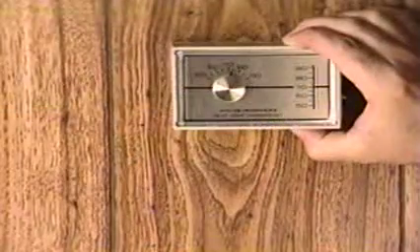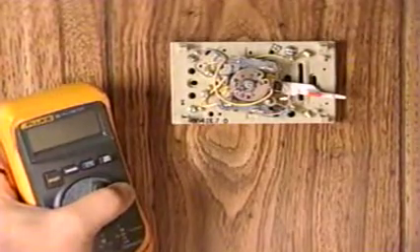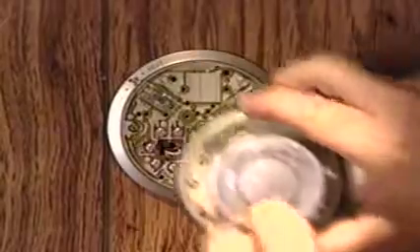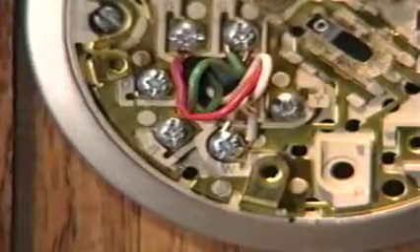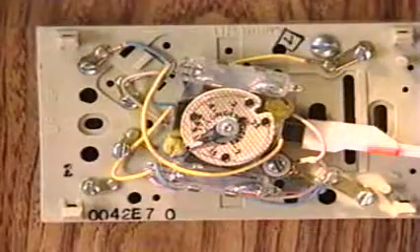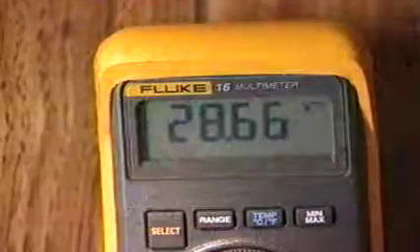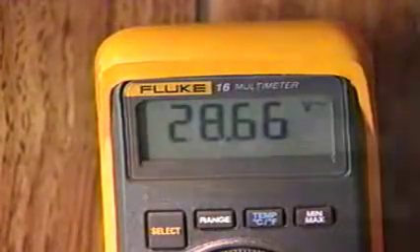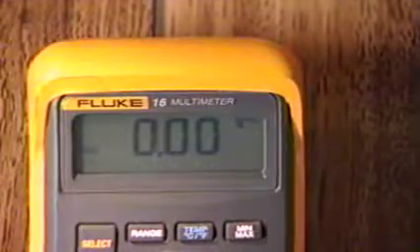A voltmeter is probably the most useful piece of test equipment when troubleshooting thermostats. Voltage readings are often taken at the sub-base, which is where the control connections are made for the thermostat. If the contacts on the thermostat are in the open position, there will be a voltage reading between the two terminals. If the contacts are in the closed position, there will be a voltage reading of 0 volts. Some thermostats control only heating equipment, some only cooling equipment, and some control both.